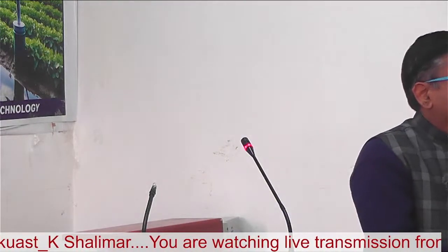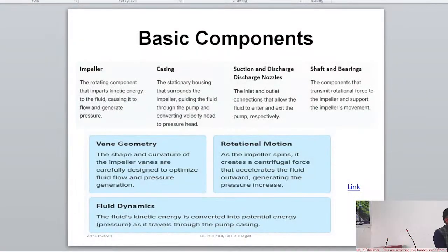Water flows off the impeller and into the volute, where it hits the wall of the pump casing. This impact converts the velocity into potential energy or pressure. More water follows behind this, so a flow develops. The volute channel has an expanding diameter as it spirals around the circumference of the pump casing. As it expands, the velocity of the water decreases.